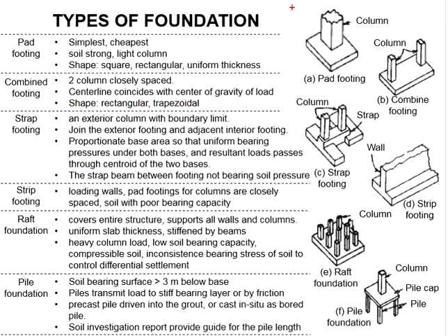Pad footing is normally used when the soil is relatively strong and the column is lightly loaded. It basically comprises a footing directly in contact with the soil, with a relatively large contact surface area, in order to distribute the stress due to the loading from the column to a stage where the pressure acting onto the soil is less than the bearing pressure of the soil itself.